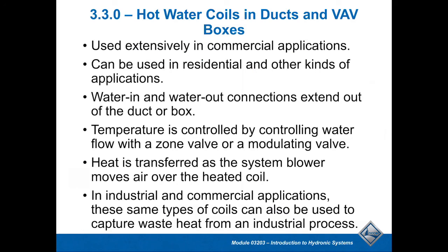So hot water coils in your air ducts or your VAV boxes, again, very commercial when you're starting to talk about these applications. In the northern climates, you typically see a lot of hot water used. In the southern climates, you typically see much more electric heat used and not the hot water. And again, the hot water systems by far are more efficient than the electric side of things, but there again, you have to kind of recognize or look at what they're doing.